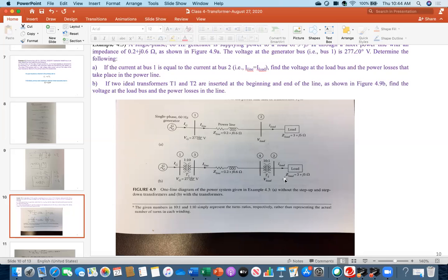How about number two? So now there is a transformer. Of course, it looks like it is connected in series, but is there any direct connection? Because the coils are completely separated. So the question is, how would you know the current value here? If you can know the current value here, then you can multiply with the impedance and you will be getting the voltage. And how would you find the total current here? Like in this case, as I told you, you will be summing up this load and this load, this impedance and this impedance. That is your total impedance.